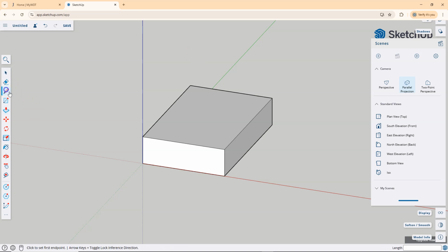And then just like before, we're going to create that ridge line from midpoint to midpoint, front to back. Now I've already done the math on this. I know that if I pull this ridge up 7.5 feet, it'll give me an approximately 6 and 12 slope. And we find ourselves doing that sometimes. You can get an exact slope. It just takes a lot longer, and it's oftentimes not worth the effort because we are doing conceptual design typically when we're doing SketchUp. So let's go ahead and select that ridge, and then we're going to move it straight up along the blue axis, 7.5 feet. Enter.